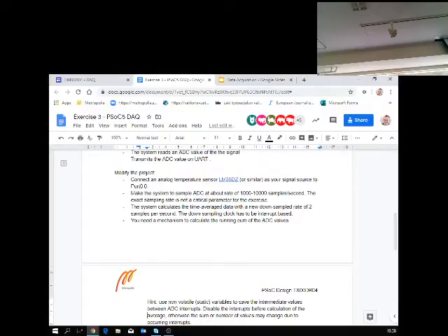When you are looking at the bottom side, then you are quite sure that these are the pins. But if you are used to looking at data sheets from the top side, you will reverse the polarity and you will burn these. Okay, now you have been warned.